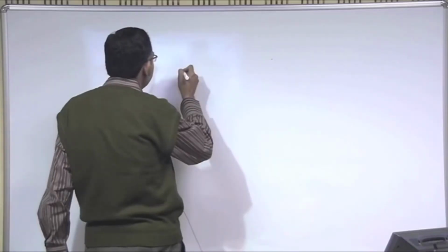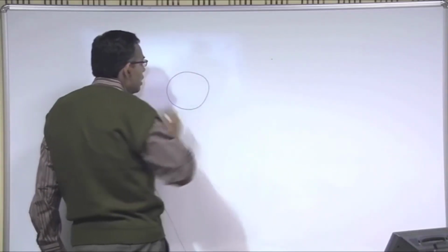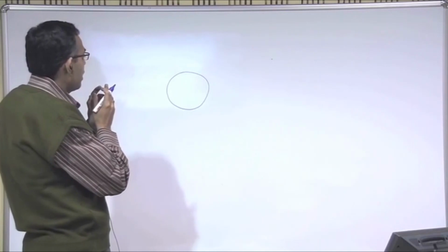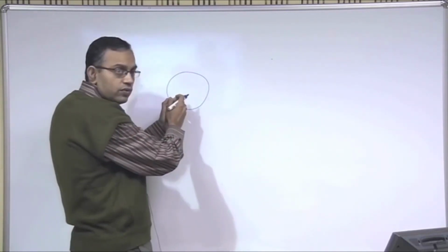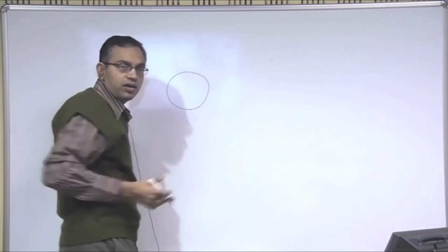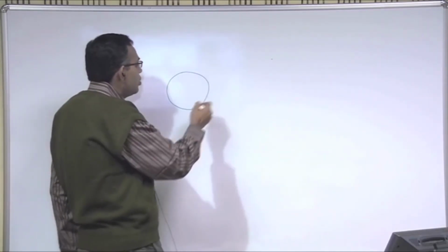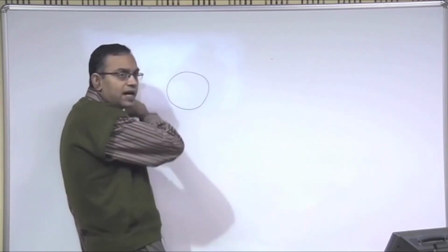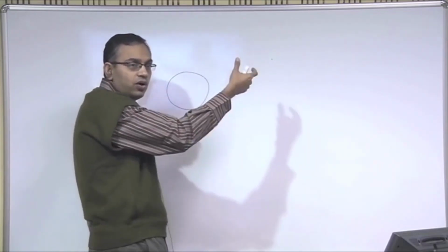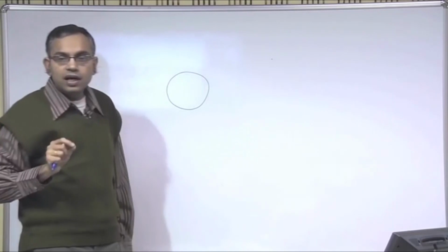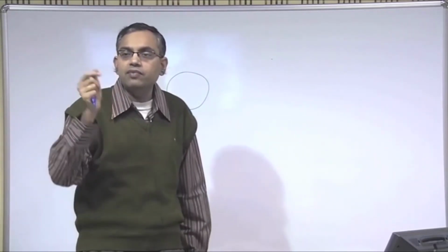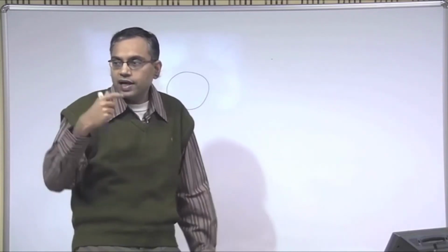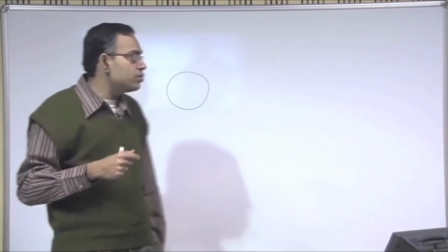this is your control volume. Now you can sit with a camera targeted at the control volume and see whatever changes are taking place across it. Something comes in and something goes out, some change is taking place within it, and you are not bothering about where that something has come from or where it will go. So you are not tracking individual particles, and tracking individual particles in fluid mechanics is a very difficult job, because fluid elements are continuously deforming during motion. So it is very difficult to track individual fluid particles.